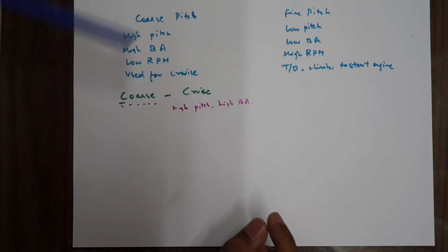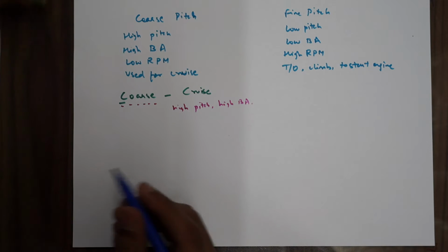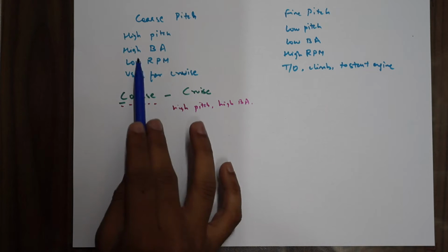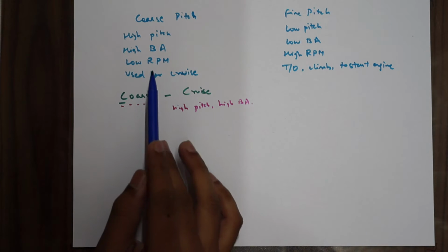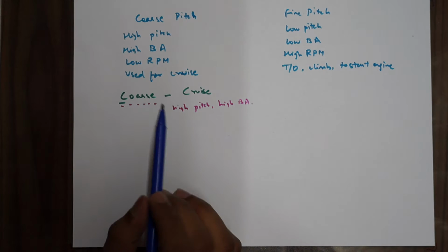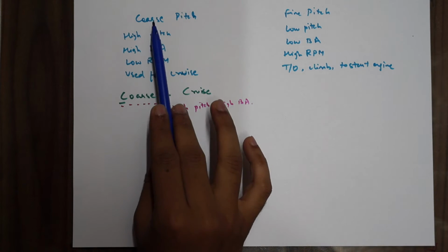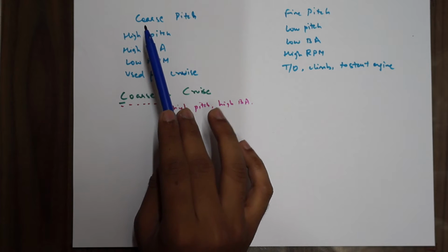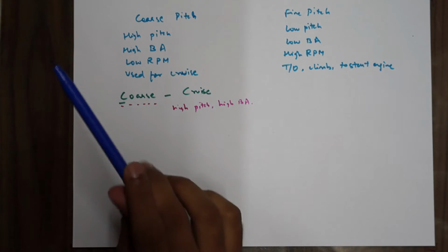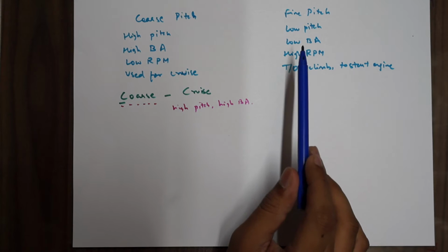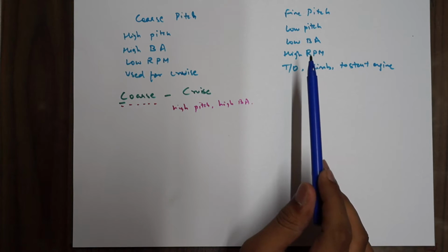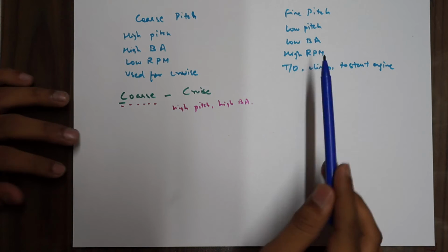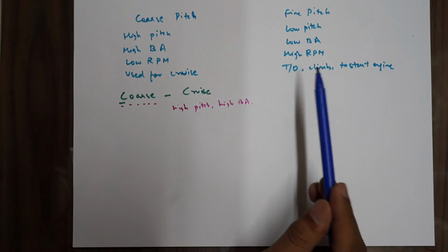And the other way is the opposite, and just the RPM is the one that is low. Because in the cruise anyways your RPM will be low, right? So that's how you can remember. An aircraft should never be taken off in coarse pitch because it'll experience loss of power. And when the aircraft is switched off, it should be switched off on fine pitch to have less load on the next run. Whenever it is started again, there is less load.